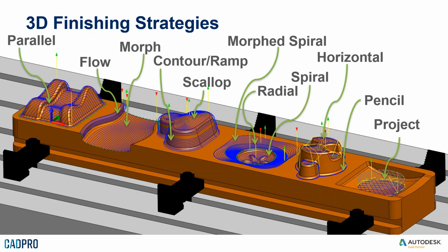Now, the downside to a toolpath like Flow is when you're creating fillets, for example, in your modeling environment, it's quite easy to end up with poor geometry, as the CAD system is trying to fudge geometry to create a valid fillet. In that scenario, when the CAM system extracts all of those underlying wires from the face, you can end up with converging toolpaths that twist inside out, and you just get horrible results. So right tool for the job.